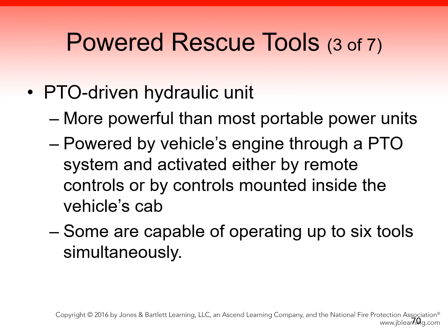During the operation of tools, the pressurized hydraulic fluid will move from one section of the system to the other through the hydraulic hose lines, pressurizing the system, and then returning to the hydraulic fluid reservoir. Hydraulic hose lines are usually kink-resistant and electrically non-conductive. They are constructed with several reinforced layers of thermoplastic or rubber material. The method used to couple the hose lines will differ depending on the manufacturer. Driver operators should familiarize themselves with the correct method for coupling and uncoupling hydraulic hose lines for their department equipment.